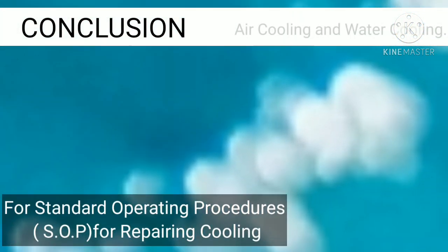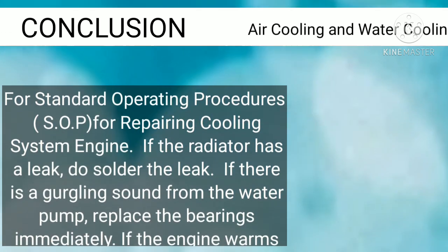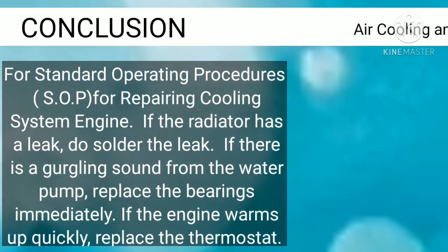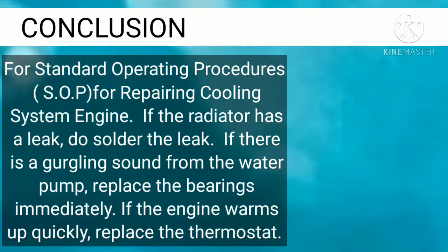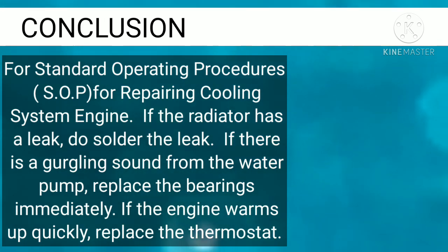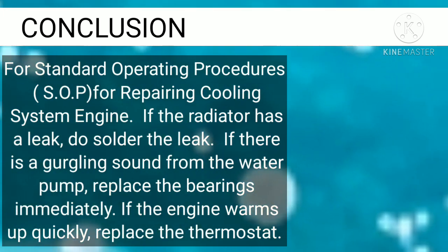The conclusion is for standard operating procedures, SOP, for repairing cooling system engine. If the radiator has a leak, do solder the leak. If there is a gurgling sound from the water pump, replace the bearings immediately. If the engine warms up quickly, replace the thermostat.